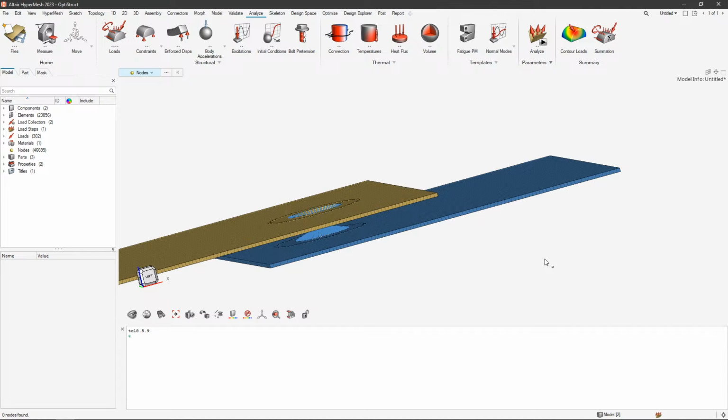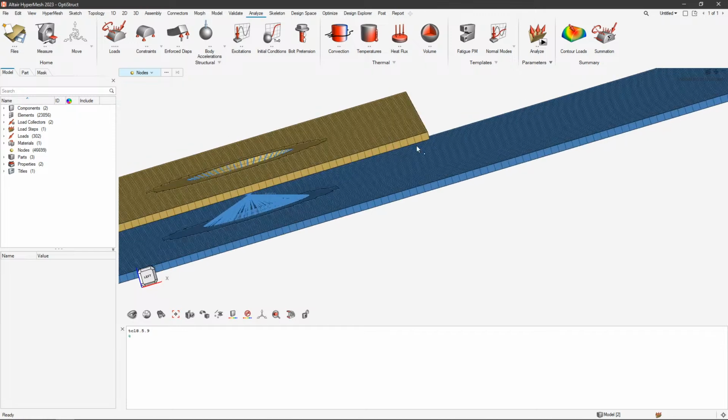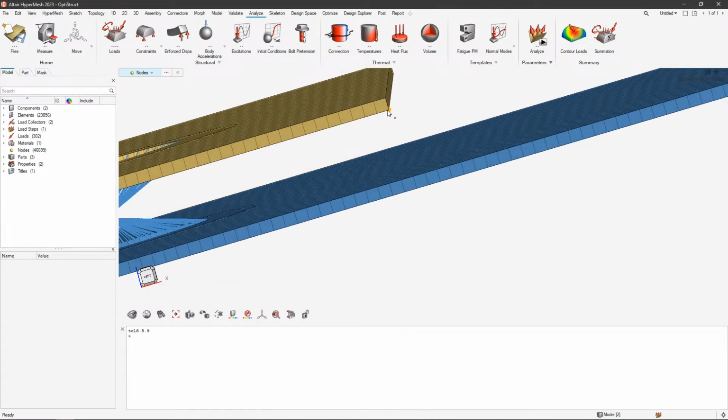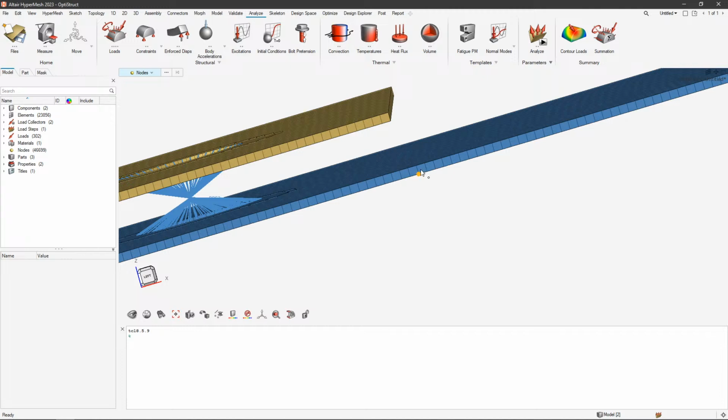Because now we can safely assume that, at least to my knowledge, I cannot think of a configuration of the RBE for which this would break. The only thing which would break that is if you have a connection which is the same node of two nodes here, because then yellow and blue would be seen as one part. This will break it. All other things will not break it.